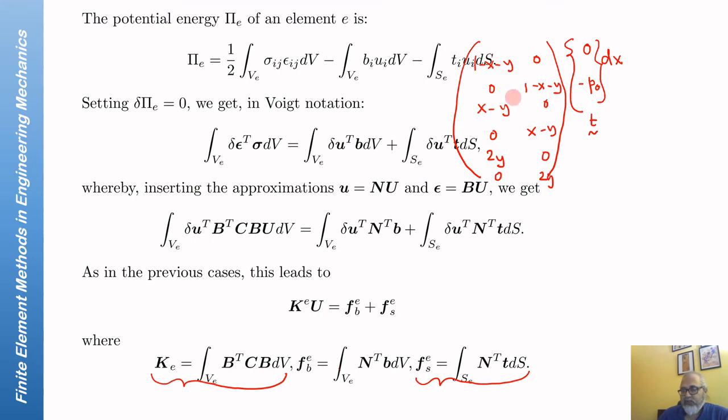This is your n transpose. We're calculating this. We'll integrate from 0 to 1 of dx, and that will give me the elemental force vector.